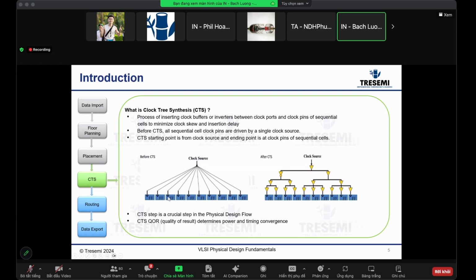It has to figure out how many loads, how many endpoints, how many sync pins it has per clock tree, the distance, where they sit, the insertion delay, the current delay, and then it will try to balance by inserting buffers to balance all the different endpoints, so that all the clocks will arrive at different flops across the chip at the same time or within that small clock skew window. So it has to traverse down and figure all that out before it actually does the insertion, the balancing, and the delay.